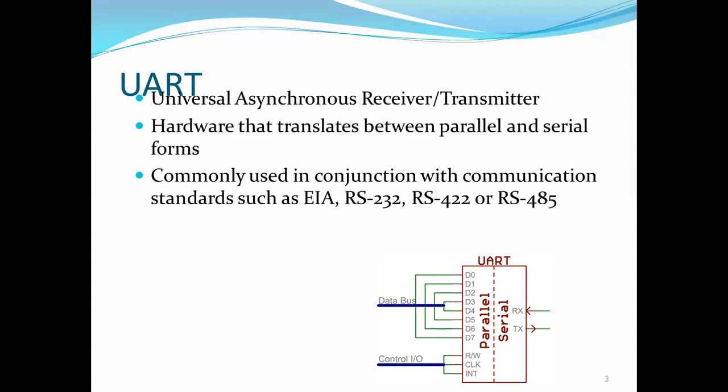It receives and it transmits also, but it is an asynchronous hardware that translates between parallel and serial forms. It is commonly used in conjunction with communication standards such as EIA, RS-232, RS-422, RS-485.